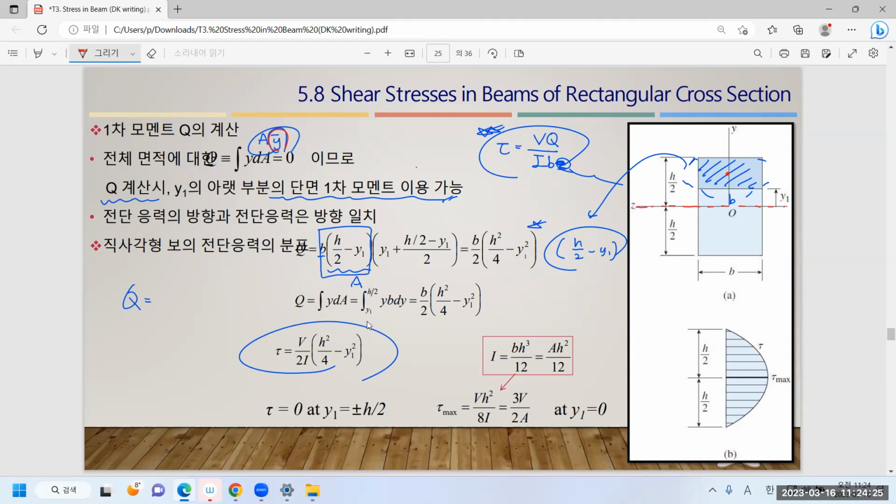From here to there, this is actually the question. And what we have is the y1 information. And just now we talked about this height that was here. So height over 2, that is this part, isn't it? So you can utilize this information, h over 2, and bring it plus y1. That should be the total distance. We call it y bar, isn't it?